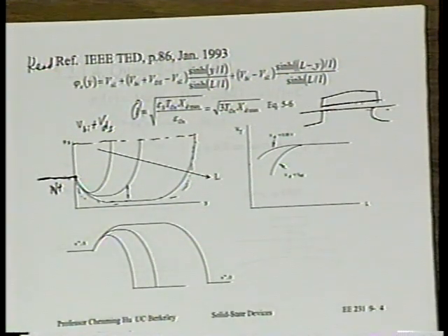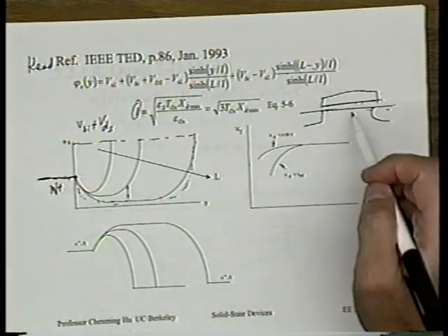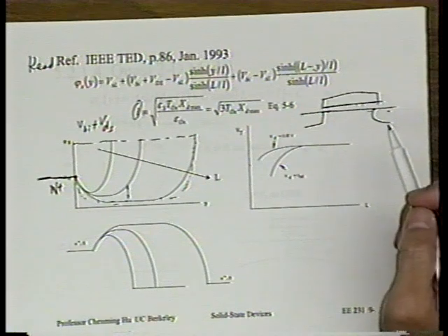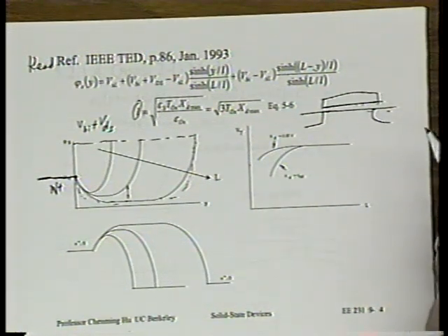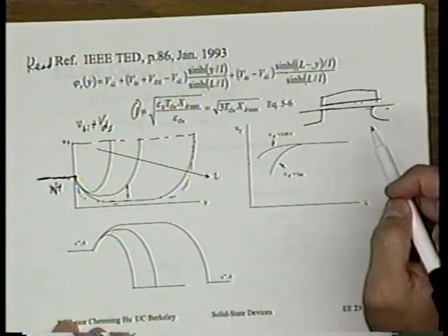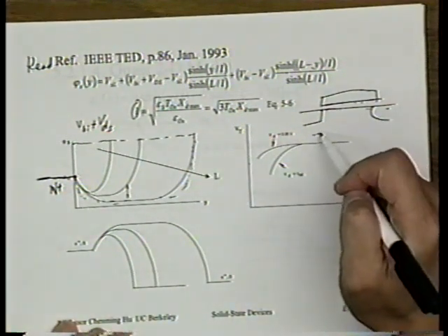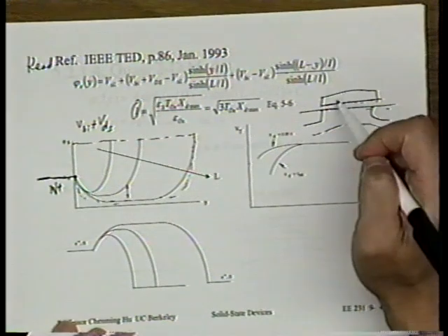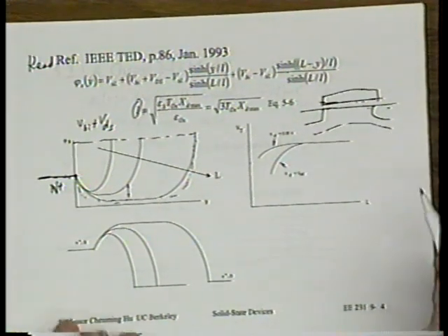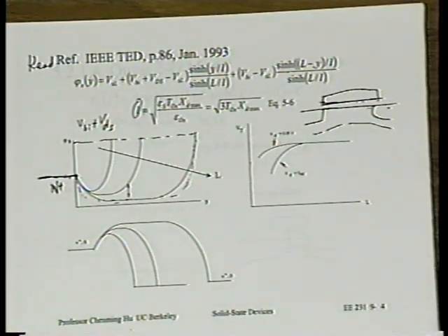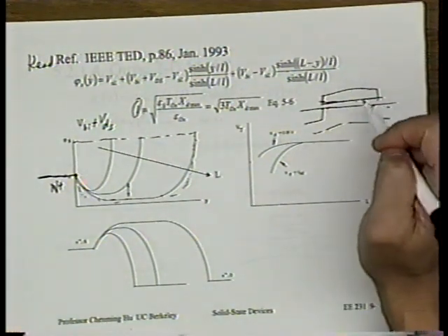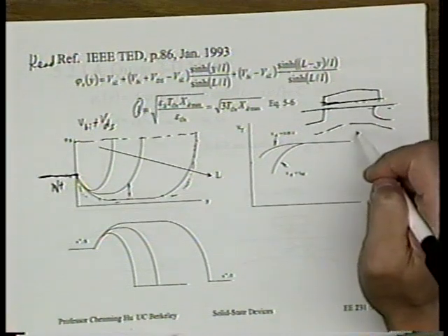Why is that? Well, you can say this is because the xd max term is large, but that to me is still not that physical. It's more mathematical. The physical way to think about it is that xd max and the gate oxide thickness play a very similar role. A few lectures ago, I encouraged you to remember there's a back gate.